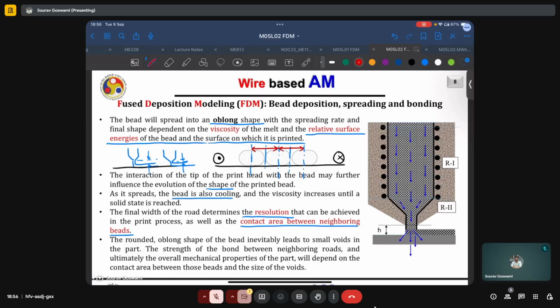But for a different process parameter, the bead may spread more, or it may even shrink down. And in that case, you will have either, say, excess overlap than you planned, or a lack of fusion between successive tracks, or intertrack porosity.